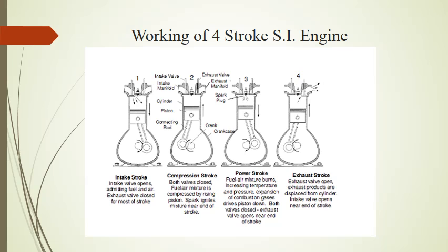Suction stroke starts when the piston is at top dead center and about to move downwards. The inlet valve is open at this time and the exhaust valve is closed. Due to the suction created by the motion of the piston towards bottom dead center, the charge consisting of fresh air mixed with the fuel is drawn into the cylinder. At the end of suction stroke, the inlet valve closes.